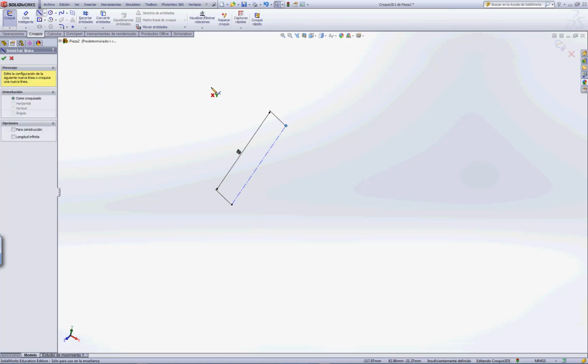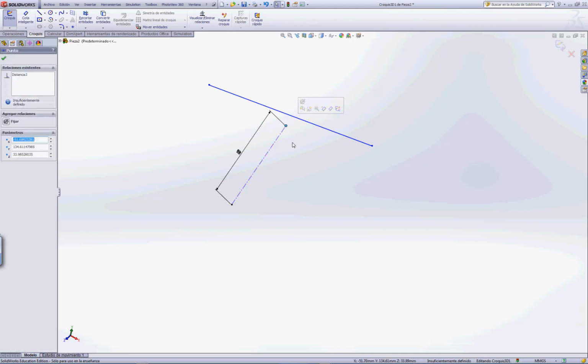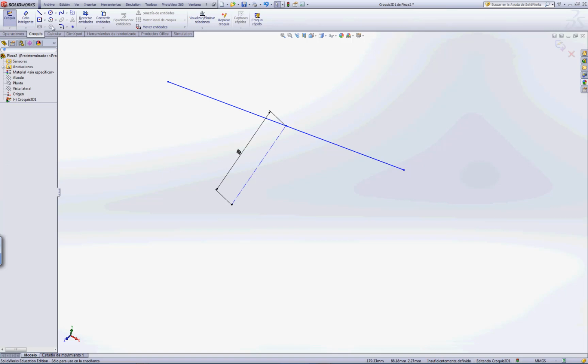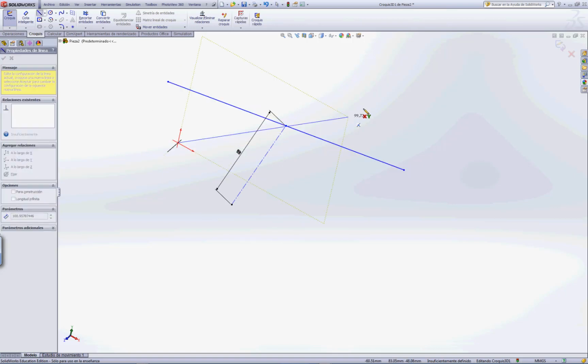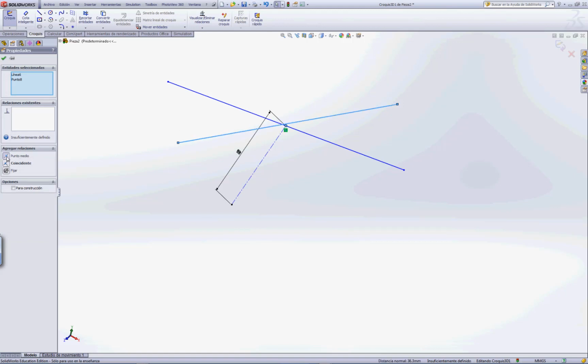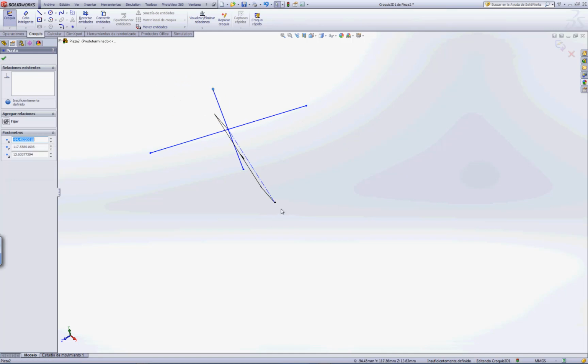We will be sure that the plane is then perpendicular to the segment. So we are going to start drawing the lines to define the plane. We need to make the first line coincident with the point of tangency between the plane and the sphere. I'm going to set the coincidence at the middle point of the line to avoid that when we rotate the view afterwards, any of the lines will move away. And now we see that we have the two lines intersecting and containing the point of the surface of the sphere.